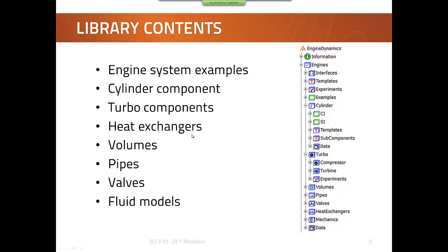There are also some fluid models. There are mixes for exhaust and air using the NASA expressions. And there are also simplified gas models assuming a linear CP for the gas. And that is good because that leads to a fully explicit model. So we do not have any nonlinear systems in this model either, which greatly improves the performance.